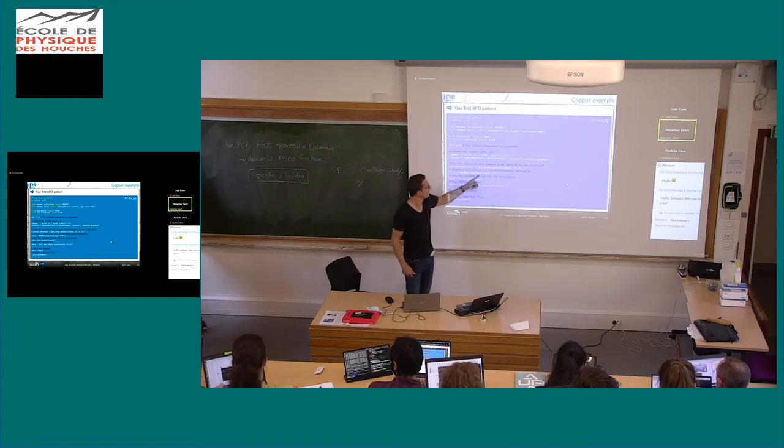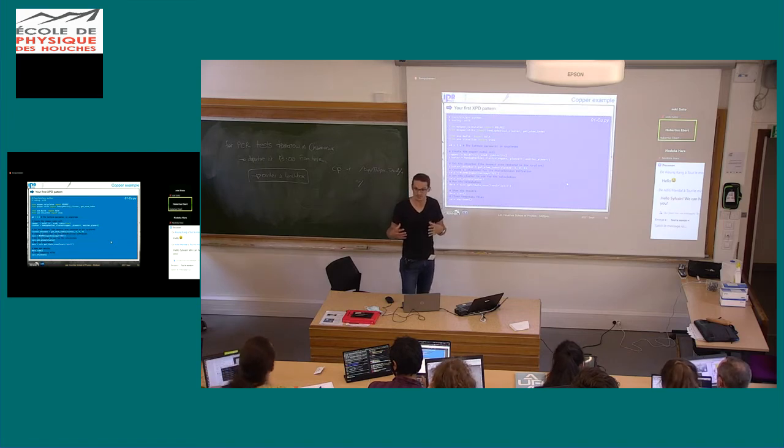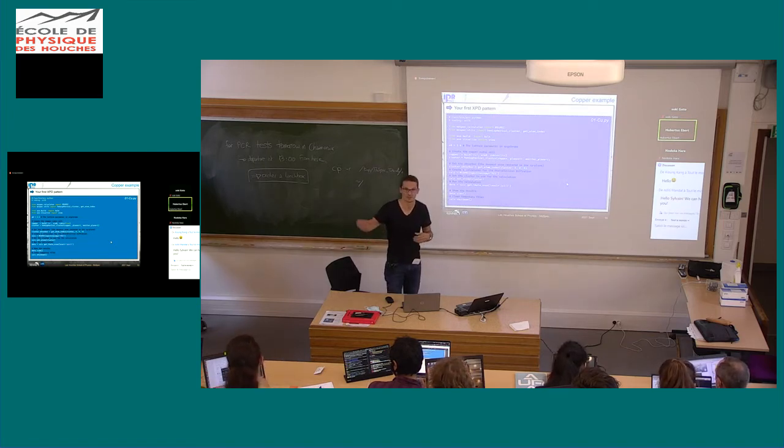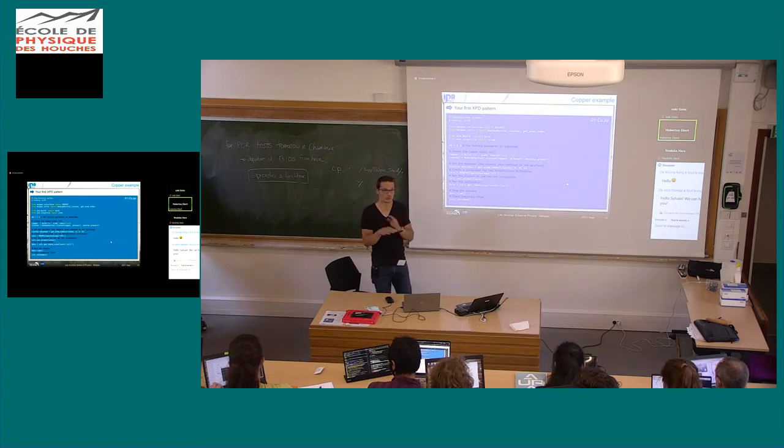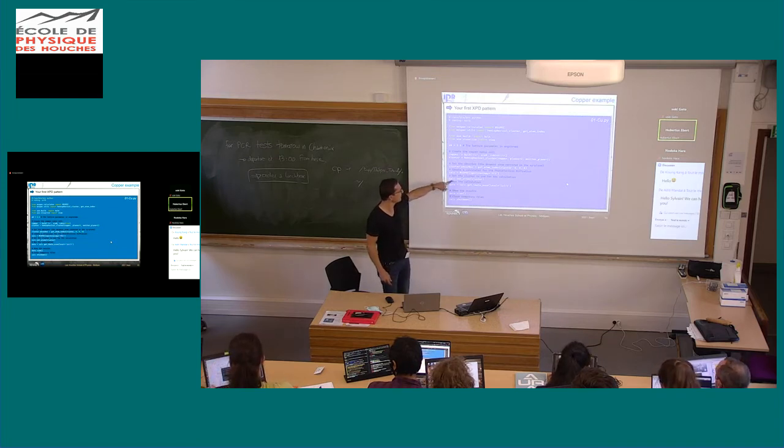There are other options, for example, the algorithm to use to compute. Like Didier said, there are several algorithms that we use to compute the result of photoelectron diffraction. So the total matrix inversion, which is the complete result, and some approximation with the series expansion or correlation expansion, etc. For the moment, only inversion and expansion algorithms are supported. And this is enough to compute for the moment a large majority of structures. So you created your calculator, and then you tell your calculator that you will use that cluster. So calc.set_atoms, I will use the cluster that I produced with the hemispherical cluster function.